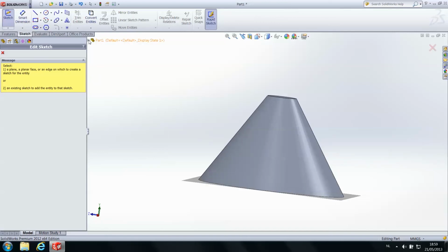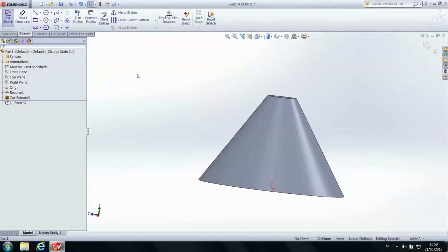So you can select the planes by clicking this little thing, and then you have three planes here: the front plane, top plane, right plane. I'm gonna go for the right plane now. So now I'm going to work in the plane that is lying inside of our screen.